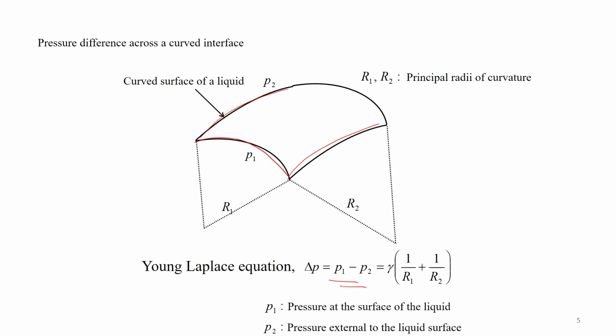Suppose in the capillary problem the meniscus is something like this, in a capillary of circular cross section, and let us say this is a wetting liquid, so the angle theta is almost equal to 0. The pressure here is P1, and the pressure here is P atmosphere. In that case we can show that P atmosphere is greater than P1, which is why the meniscus goes down.